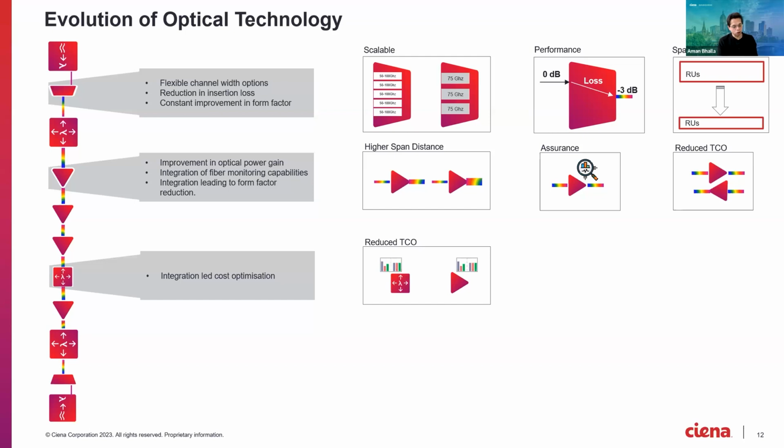So if I talk about cost factors, filters are usually cheaper than amplifiers, and amplifiers are usually cheaper than ROADMs. But the best way to use a ROADM is for optical switching or steering a wavelength. If you just deploy a ROADM for gain equalizing, which has been happening all this while, then you're losing out on quite a valuable amount of money for just gain equalizing.